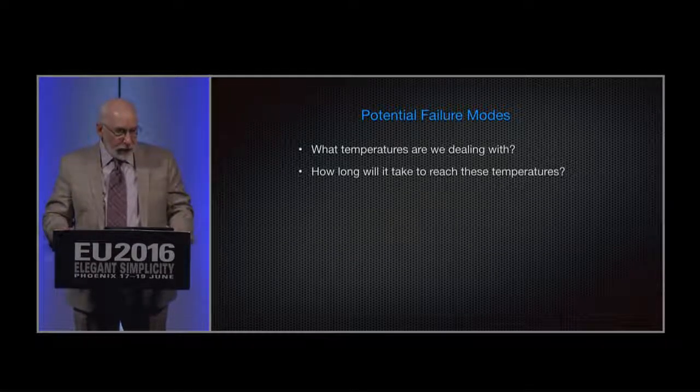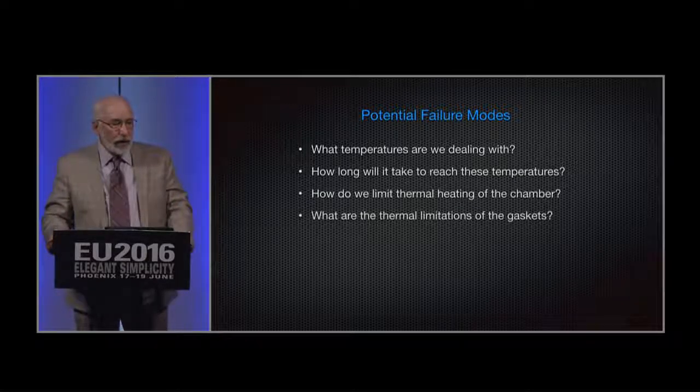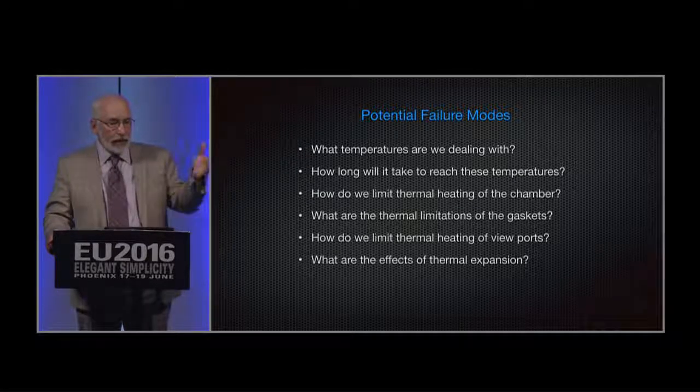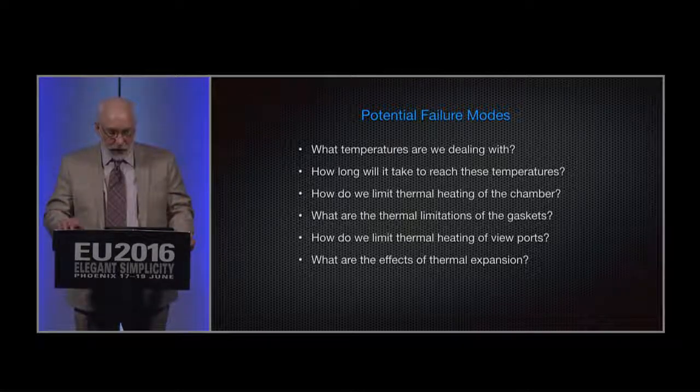So potential failure modes. What temperatures are we dealing with? How long will it take to reach these temperatures? How do we limit thermal heating in the chamber? What are the thermal limitations of the gaskets? How do we limit the thermal heating of the viewports? What are the effects of thermal expansion?